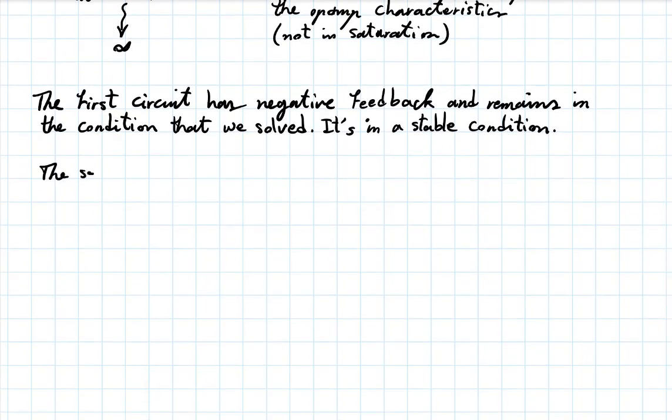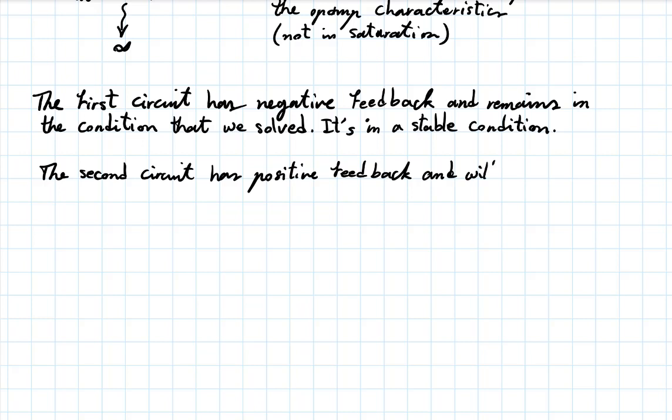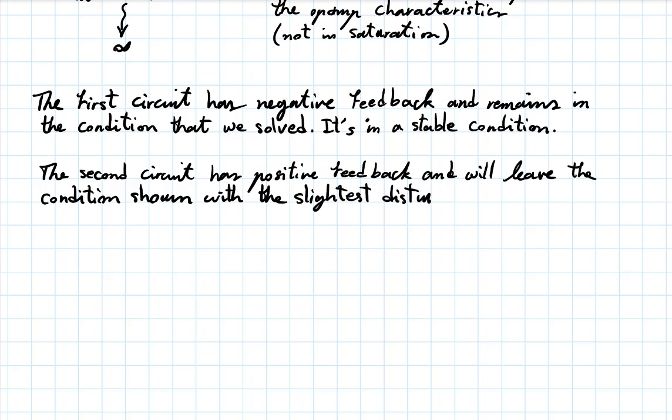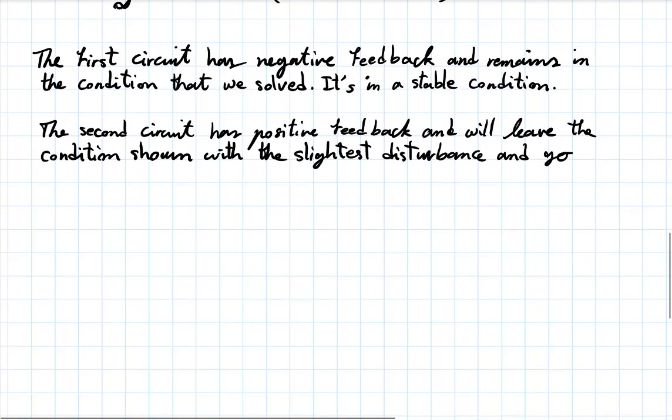The second circuit has positive feedback, and will leave the condition that we showed with the slightest disturbance, and go towards saturation. So it's unstable.